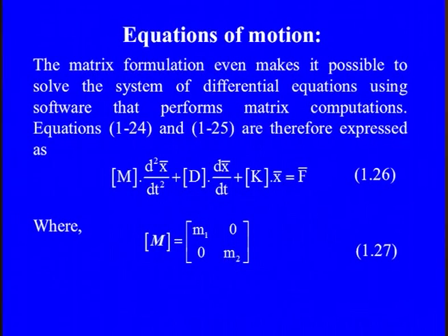And we know that when the system has two degrees of freedom, there are two natural frequencies, which are simply a reflection of the characteristic roots of the equations, and then we have the corresponding mode shapes for that. These mode shapes absolutely reflect the individual natural frequencies. We also discussed that when damping is involved, we can calculate the undamped natural frequency and the damped natural frequencies.